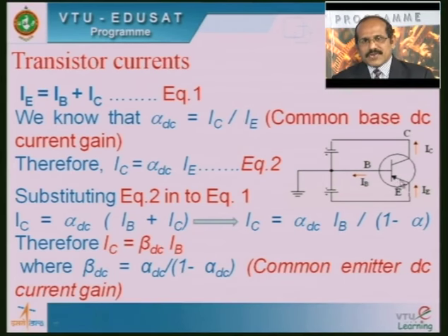So that's what you can note down from the emitter terminal here. In the emitter terminal, the arrow is always towards the N type. Therefore this given transistor is PNP. This P acts as the emitter, this N acts as the base, and the other P layer, the extreme P layer, acts as the collector here.